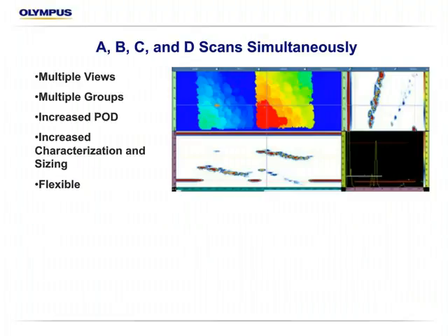So a lot of the views we look at are the same, but with phased array views we have a lot of flexibility, and we tend to look at more volumetric views. We still use the C-scan, or the top-down thickness scan, as our baseline, but from there we can start to view side views simultaneously along with the raw A-scan in order to do a really good assessment of what we're looking at. This becomes inherently important when you do have something unique beyond general wall loss, something like HIC or SOHIC, or just a mid-wall anomaly that you weren't expecting in your corrosion scan.